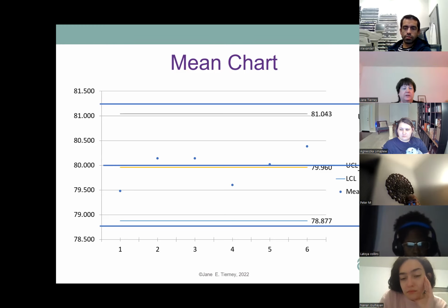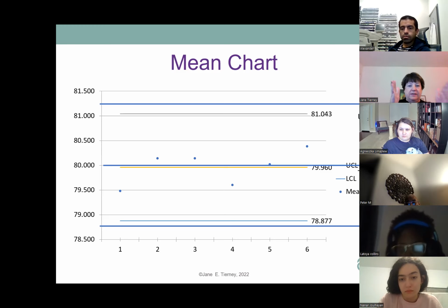That's what we're trying to do, is to come up with this chart, and we do this over time, and we track it, and we calculate the limits, the control limits, not the spec limits. The spec limits are what the designers give us to say this is good.